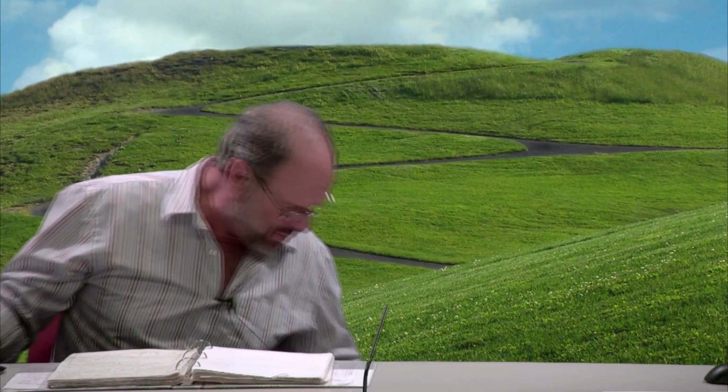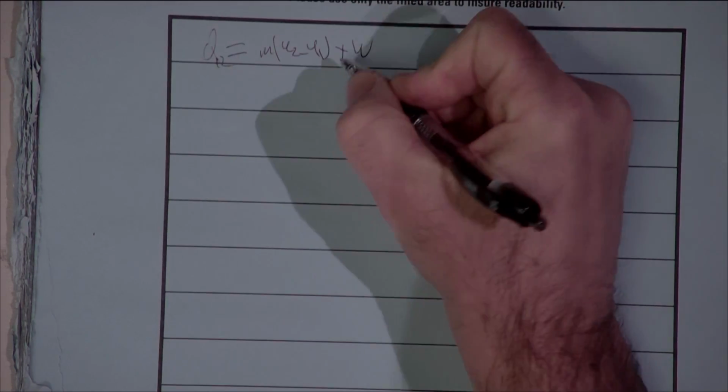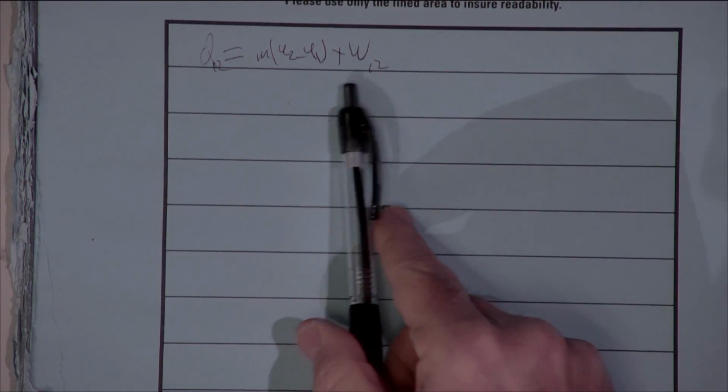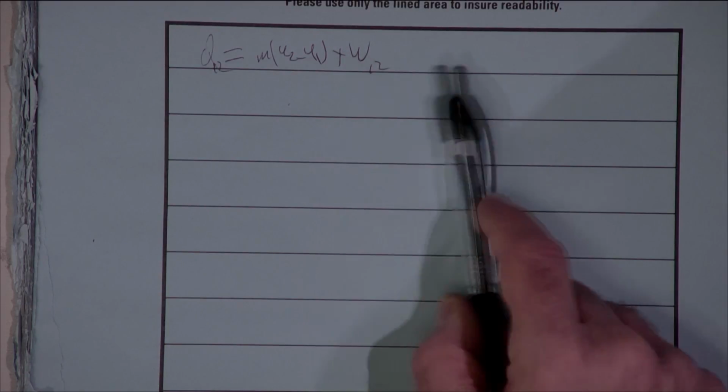All right. So one thing I do want to comment on before we continue. When you're solving problems involving the first law of thermodynamics, which is really what this course is all about, make sure you're using the right equation. The first law in its most general form tells you that heat transfer is equal to change in internal energy plus the work, right? I guess we could put little 1-2s down here. We recognize there's different types of work. It might be electrical work, might be boundary work, might be paddle wheel work or shaft work. Then you just have several work terms.